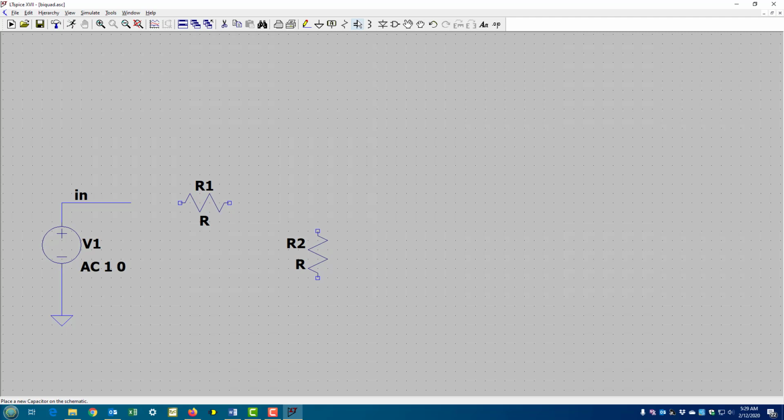Enter in the capacitor, pull a cap, left click, that's all the capacitors that I want. Right click to get out of that mode, and then we need to do some grounds, right? So here's some grounds that you can pick, maybe one here and one there. So now we have grounds, or maybe make it a little lower here. So if you want to move things, you have to go and say, for example, move, right? Here's move. You can also move components this way, okay.